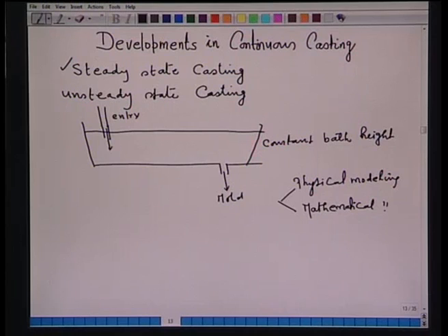Now, the whole idea of these investigations was to understand what type of flow is created by the submerged ladle stream, because the force that is responsible for creation of flow in the Tundish is the kinetic energy of the turbulent stream. In the physical model, what has been done?